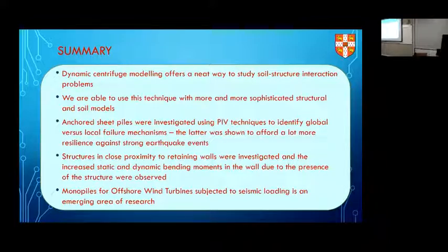They try to deform, and we design them to either deform without any stiffness so that the soil can do whatever it wants to do, like a laminar box, or we can have the boundaries match exactly the stiffness of the soil. So that if the soil wants to go into, say, the first mode of vibration, the walls do the same. Those have been considered very carefully, and we feel we have a good handle on it. So the errors due to that are fairly small. Does it answer your question?